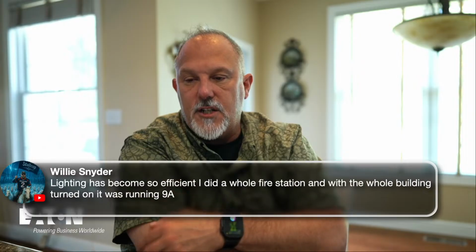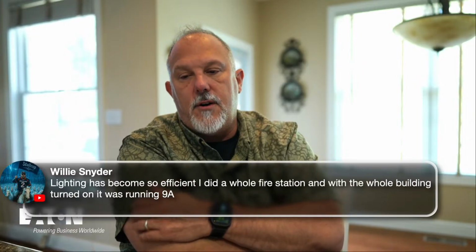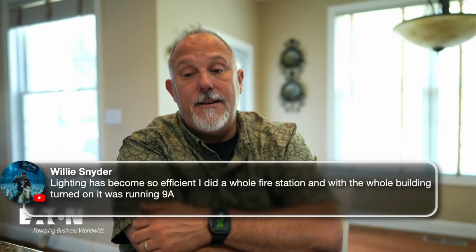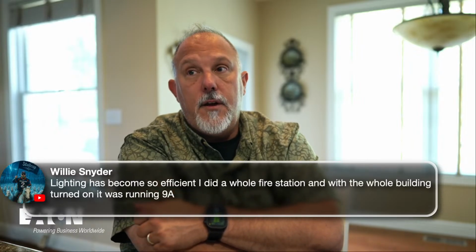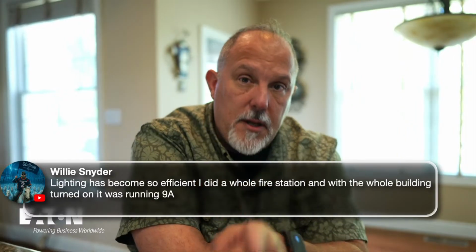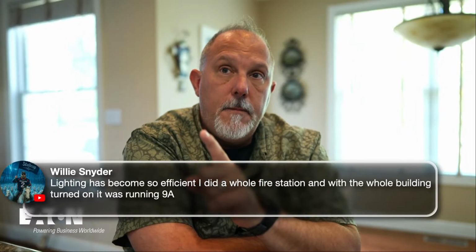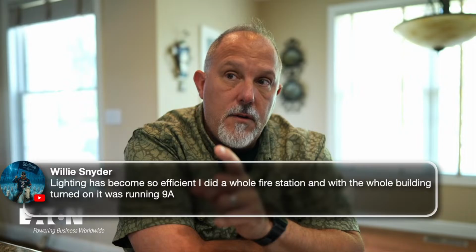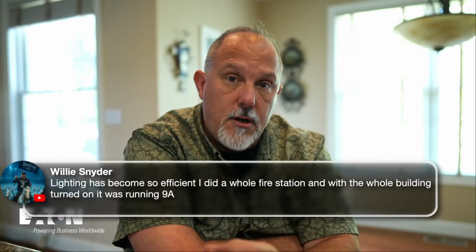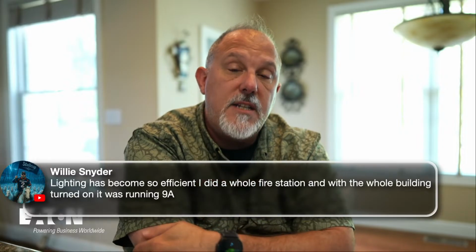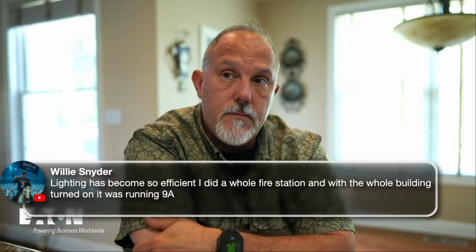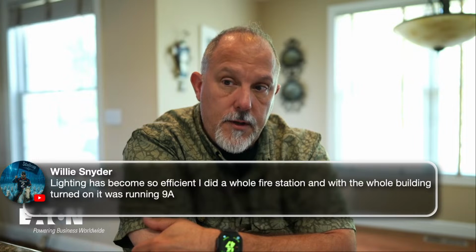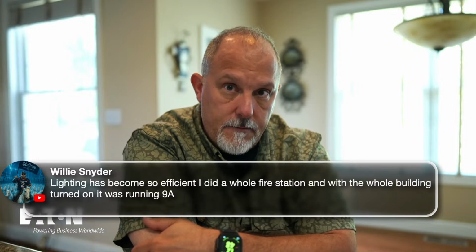I did a whole fire station with the whole building turned on. It was running 9 amps. Yeah. I tell you, Willie, if there's any place that we can save money and infrastructure costs, especially with the 10 amp breaker and the 10 amp conductors, I would argue it is in lighting.